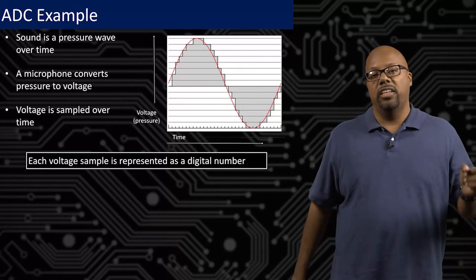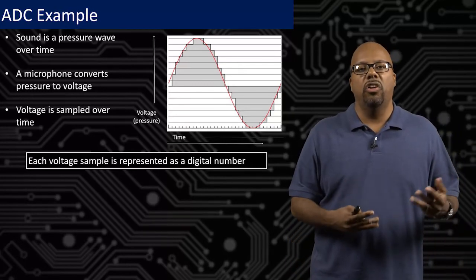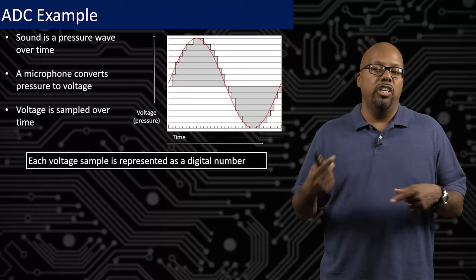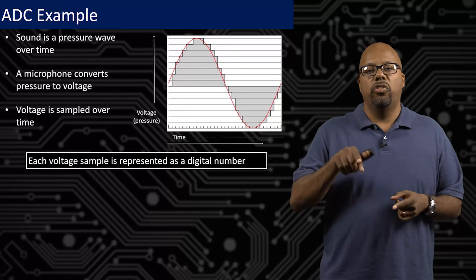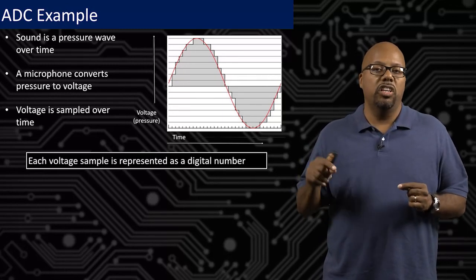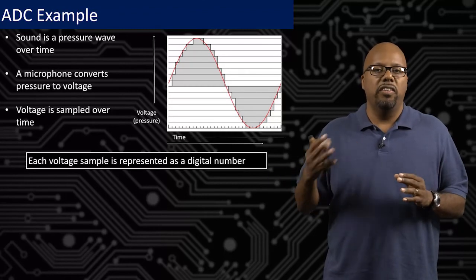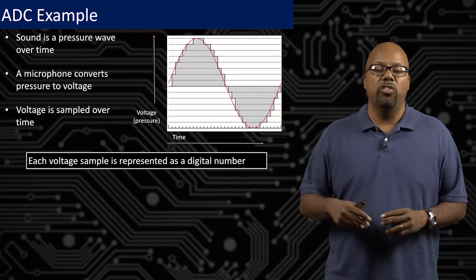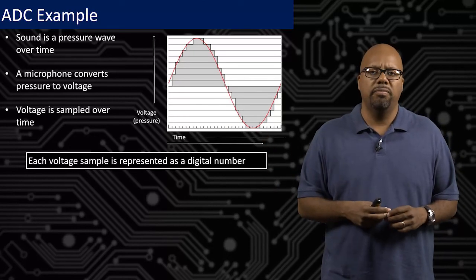And that is what analog to digital conversion does, and we need it in order to represent any kind of analog input data to the system. And note that on the outputs to the actuators, you get the opposite going on. So you start with the digital waveform, the stair-stepping waveform, and the digital to analog conversion converts it into that red, or something close to that red, smooth analog waveform that you see, and that gets sent out to whatever your actuator is, say a speaker or something like that.